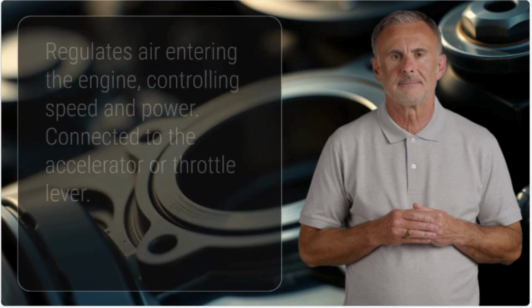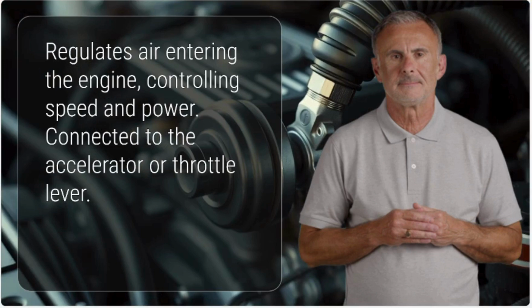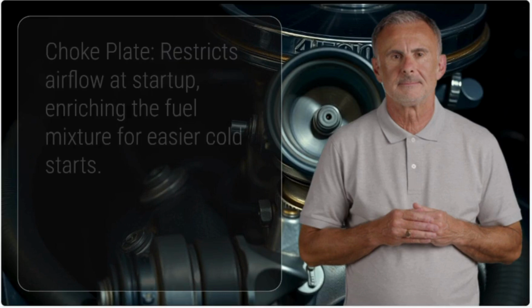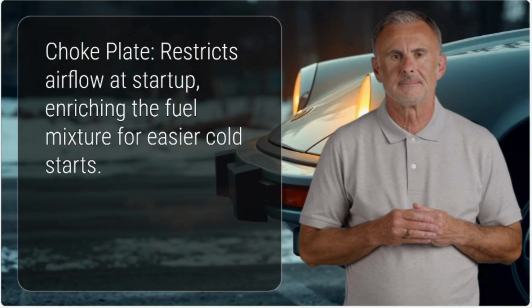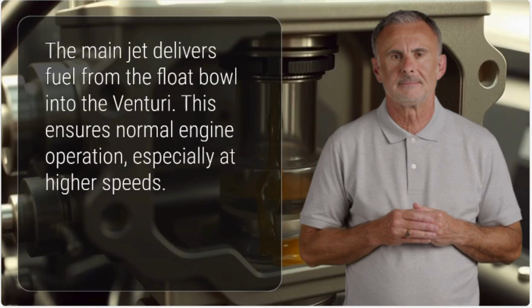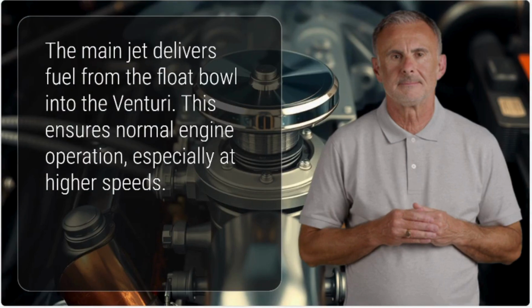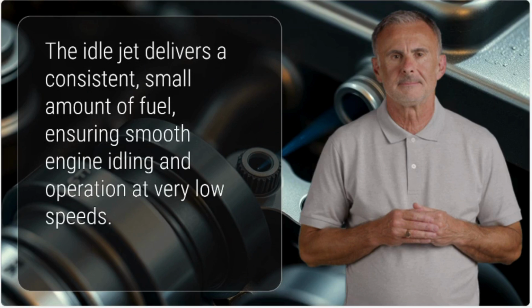Throttle plate: a butterfly valve that regulates the amount of air entering the engine, thereby controlling engine speed and power output. It is connected to the accelerator or throttle lever. Choke plate: a movable plate that restricts airflow at startup, enriching the fuel mixture to make cold starts easier. Main jet: delivers fuel from the float bowl into the venturi for normal engine operation at higher speeds. Idle jet: supplies a small, steady amount of fuel for engine idling or very low-speed operation.